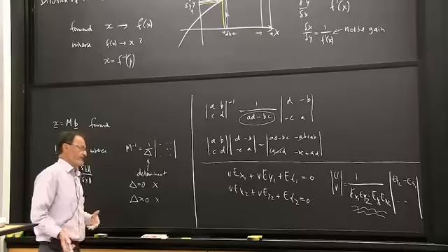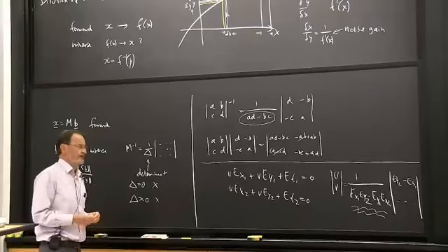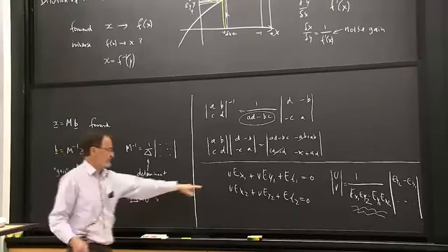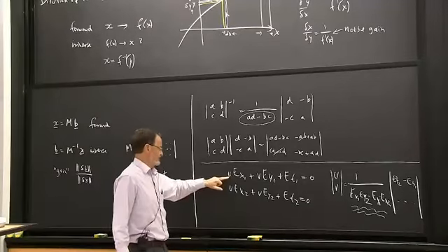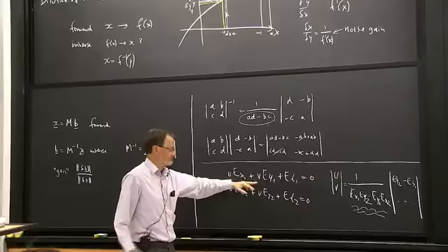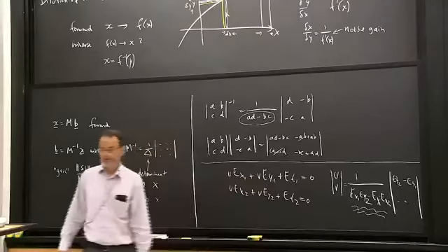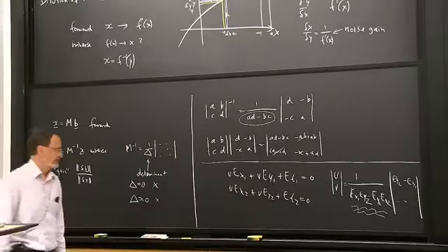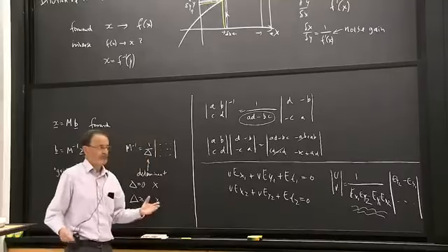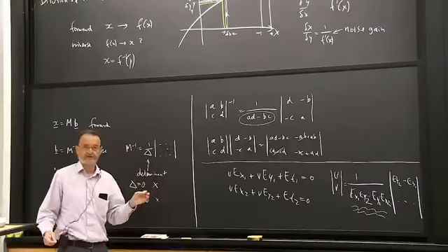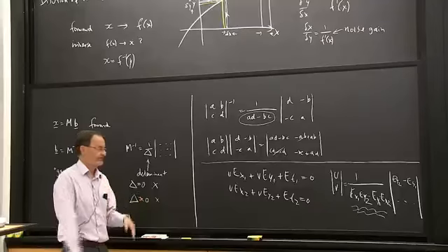And we can go into the velocity space diagram. Each of these constraints, this is a straight line. Why? Well, because it's a linear function of u and v equal to 0. So that's going to give us a straight line. This is going to give us a straight line. We're basically looking for a point in the plane that's on both lines. So we're looking for the intersection of the 2 lines.